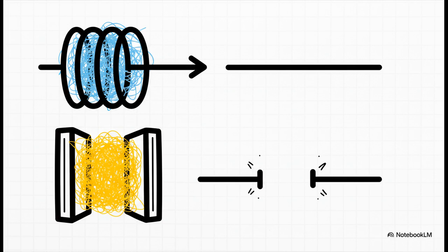Now, when we say time equals infinity in circuit analysis, we don't literally mean forever. We just mean, mathematically speaking, the adjustment is completely over. At this steady state, the physical reality of the circuit simplifies beautifully. The inductor, which is now completely settled with its magnetic field, stops fighting and just lets DC current flow freely. It acts just like a plain piece of wire, a short circuit. And the capacitor, fully charged to the brim like a totally full water tank, stops accepting any more charge, acting completely like an open circuit. The transition is absolutely finished.